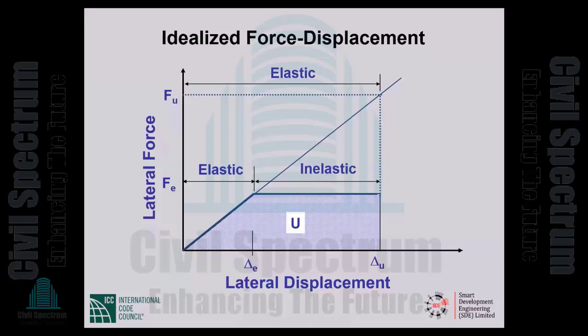So my message to you, and this is something you always have to remember: earthquake design, seismic design, however you want to say it, is a two-part affair. We design for the forces that are given, in your case, in Part 2, Chapter 6 of BNBC 2020. But then you also have to detail the structural members and the joints as required by the detailing chapter. It has detailing for concrete buildings, steel buildings, and so forth.